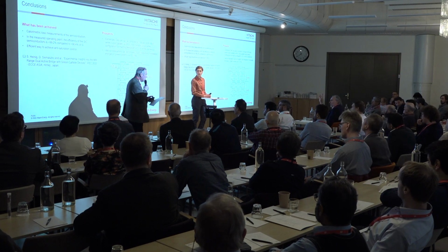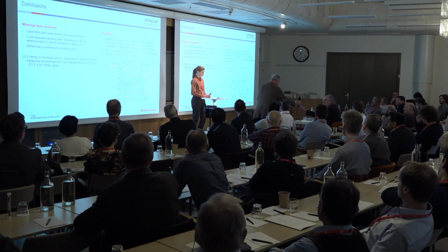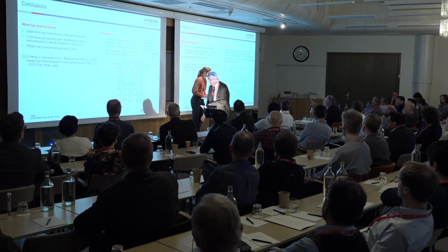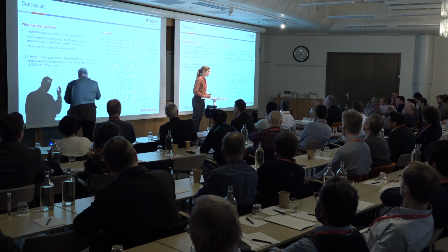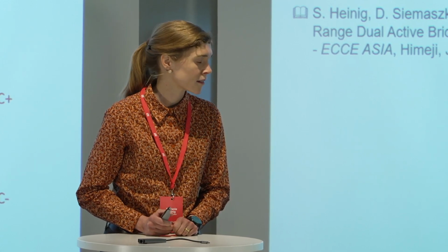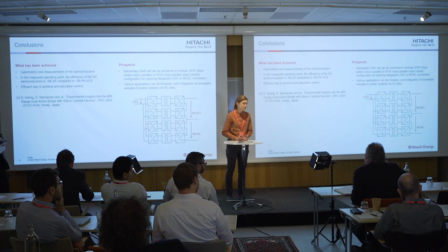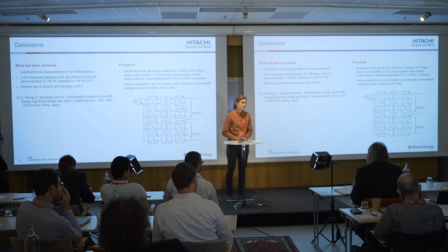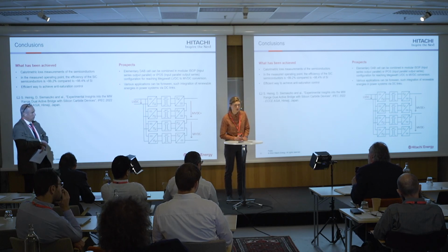So, do we have time for more? Yes? When you are combining the converters in ISOP or IPOS configuration, the medium voltage transformer basically needs to block always the highest voltage. In case of failures and for redundancy reasons, you always need to ensure that you have the full blocking capability. Where do you see limitations in terms of voltage within the transformer which you have shown?